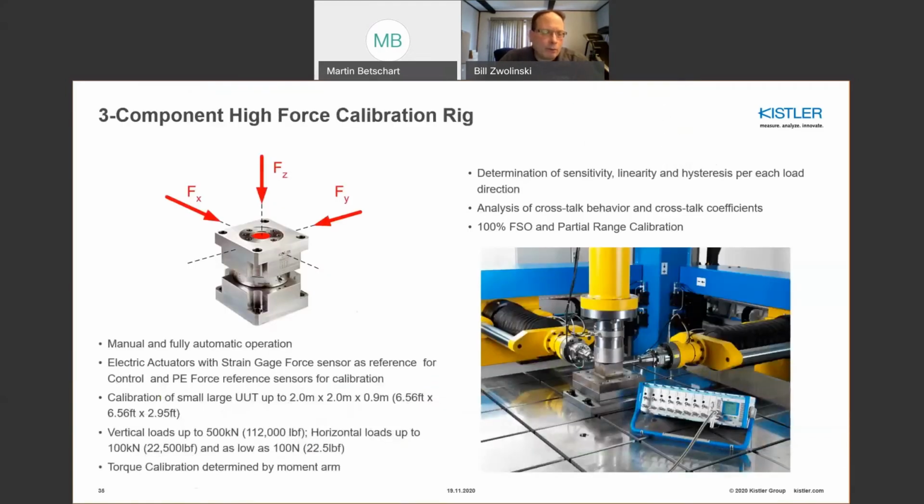And lastly, with calibration, in situ calibration at the facility can be done using static forces or weights. At the factory, we use electric actuators with reference sensors and so forth. So there are many ways to accomplish an in situ calibration, and also what we do at the factory as well. You get a calibration certificate that has all the parameters of interest.